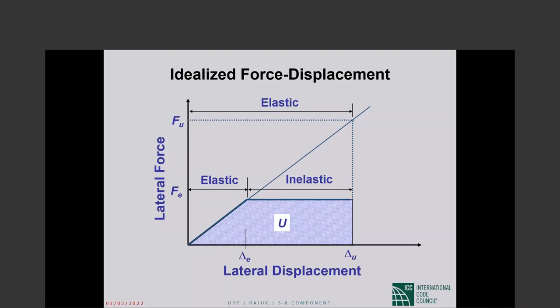The forces induced in the structure as it goes through the earthquake are plotted on the y-axis, and the displacement suffered by the structure in the process of going through the earthquake are plotted on the x-axis. Okay, so the lateral force on the y-axis, the lateral displacement on the x-axis.